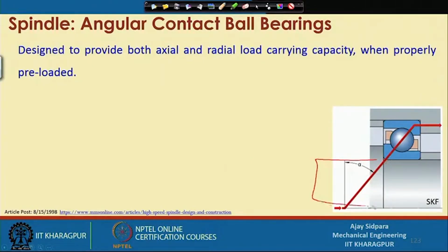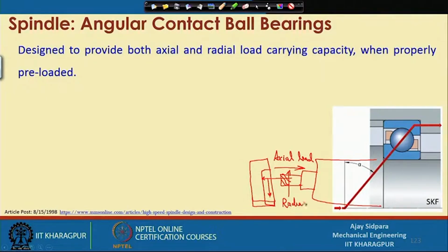Now again consider that you have a shaft, but instead of a drill you have a milling cutter, and this is your job. Now you want to create one pocket here, this is the pocket which you want to cut out of it. First, you are plunging this up to the depth. When you are plunging, at that time it will create an axial loading. And after plunging, you are giving motion in this particular direction. When you are moving, at that time your tool will experience one radial load. So at that time it will provide both the things. How it will provide, we will see it soon.